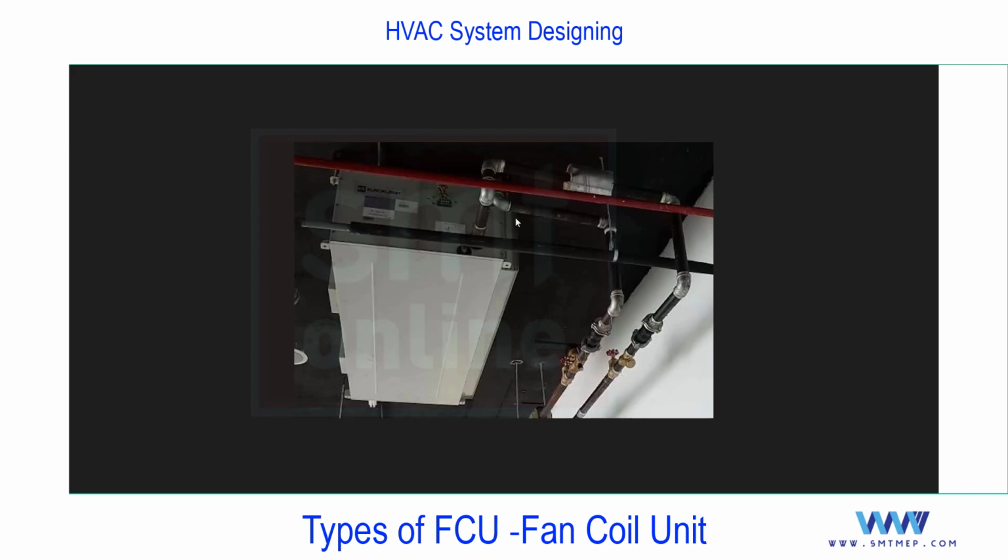At this level, this FCU is connected with black steel or carbon steel, nothing but low carbon steel or mild steel, not copper, because we are using it to supply the chill water. So this is a chill water FCU. Means as per the system, this FCU takes chill water. And this design also will be different compared with the refrigerant type. Refrigerant is nothing but the DX.